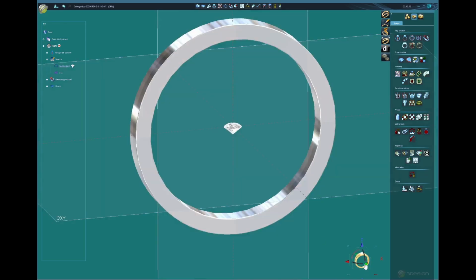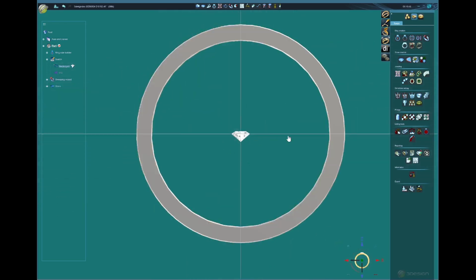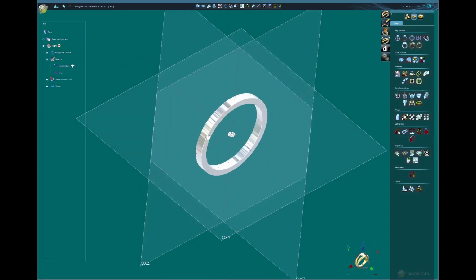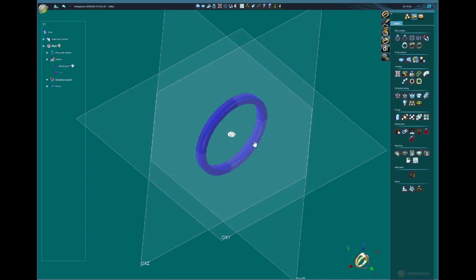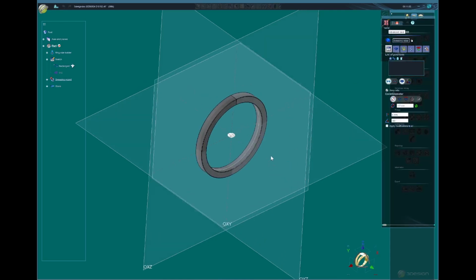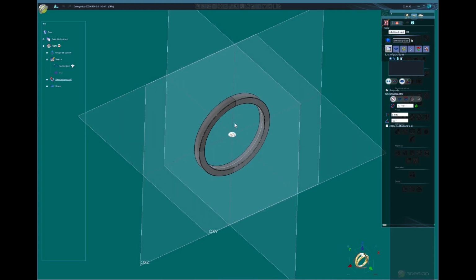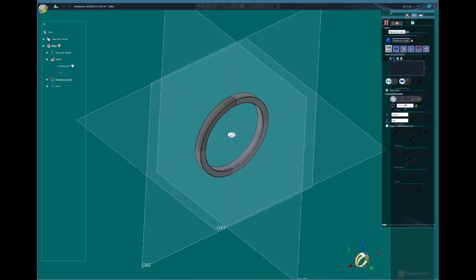Let's hide the stone flush to the plane. So now let's put the stone on top of the band. So you click the band, go to this tool here, advanced pavé, click on it, and over here, we're not going to put stone by stone all the way. We're going to speed up this process. So for that, we have here 1.7 millimeter, and you can change here as the size of your stone is going to be. In our case, 1.7 is our stone size.